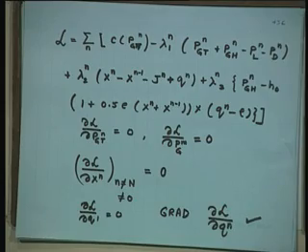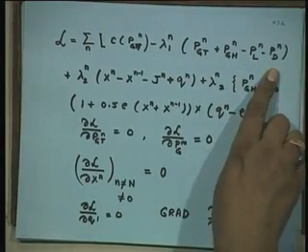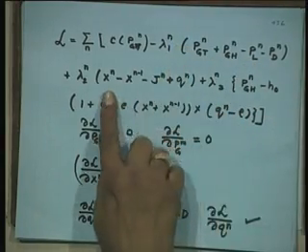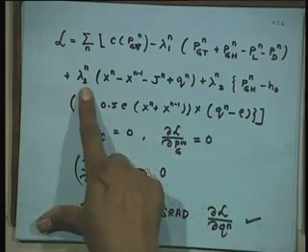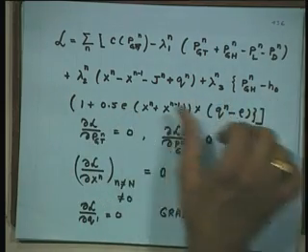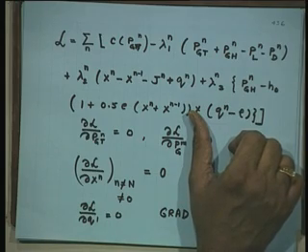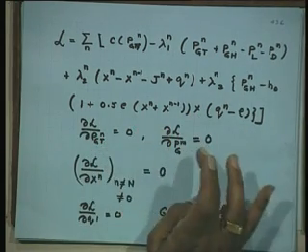Now, as usual, you formulate your Lagrangian. How do you formulate your Lagrangian? I have been talking last several lectures. Original objective function, augment it by all the constraints multiplied by dual variables, adjoint variables, Lagrange variables, lambdas. So, first constraint is power balance equation, lambda 1n. Second constraint is water continuity equation, lambda 2n. Third constraint is water power generation, hydropower generation. And then apply your Kuhn-Tucker conditions.